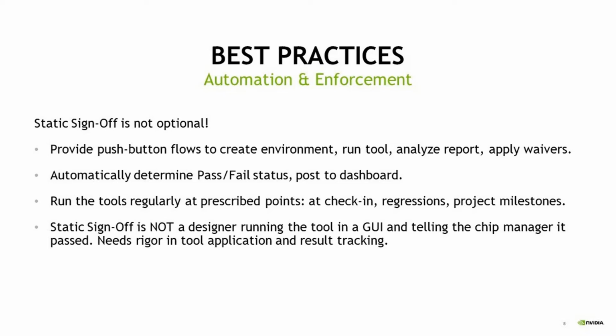So all of this is very automated and run frequently. And what static sign-off is not is somebody just running CDC one time and saying it's okay and telling their manager. It needs to be repeated and continuous so that you know that no bugs are slipping in. And our automation provides that capability.